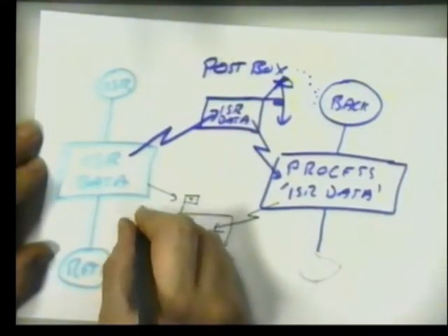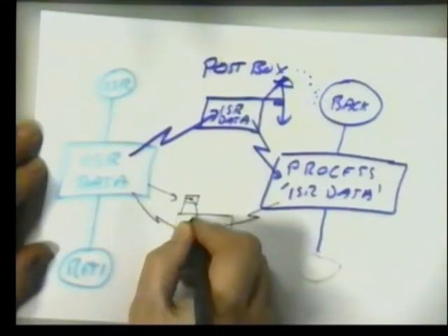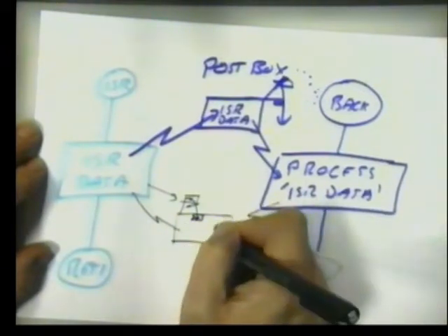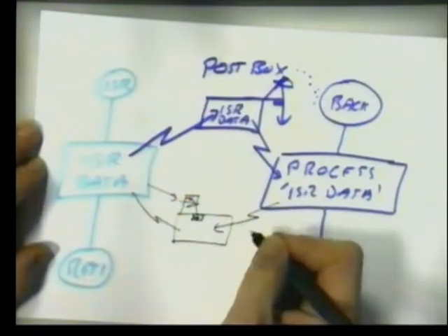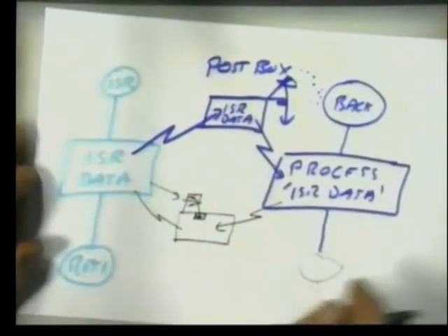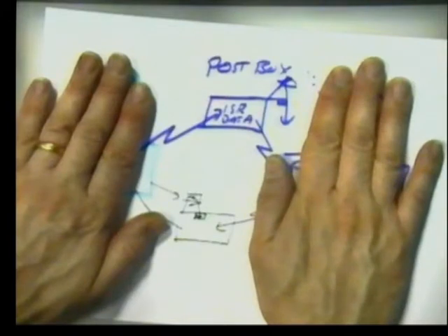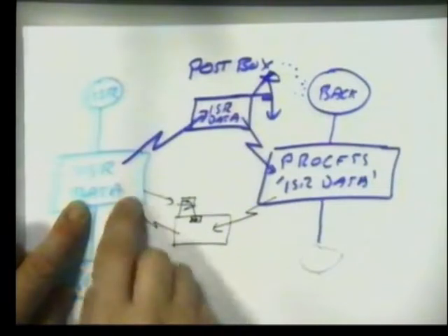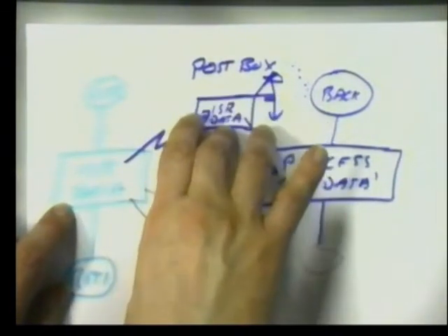And so it grabs those instructions, sets the flag to be off, false, and that signals back to the background process that the data's been read, the message has been passed. It's a very simple process. And what we have, two separate parallel processes with their own data area communicating to each other using postboxes and semaphores. You must do it. You must never ever allow parallel processes to share the same data area.